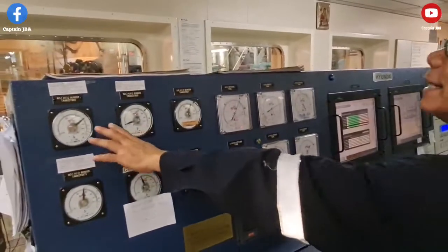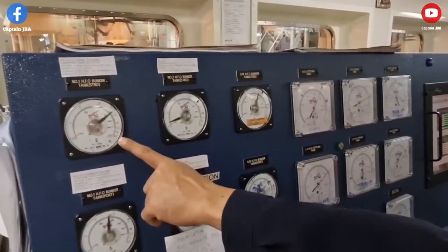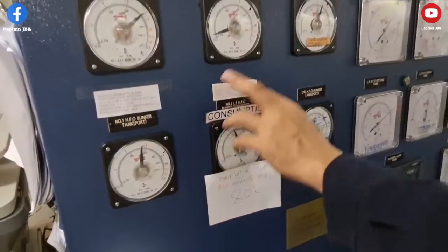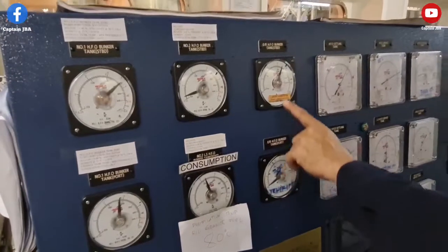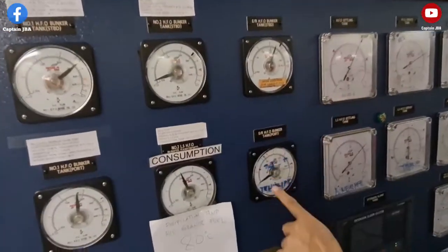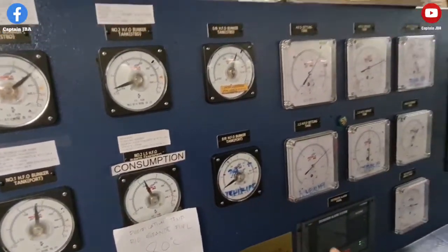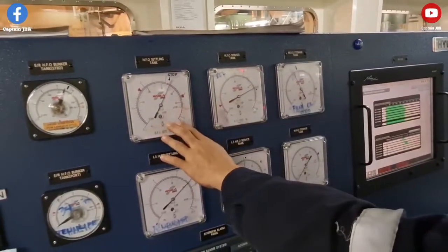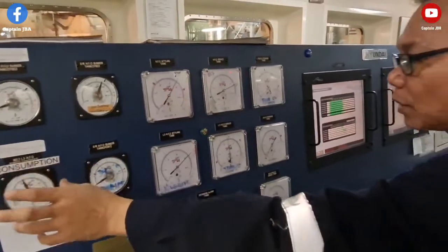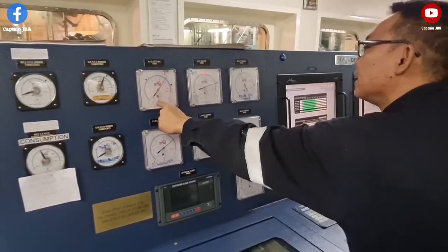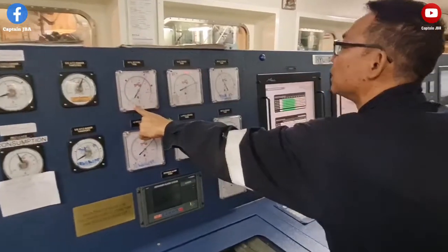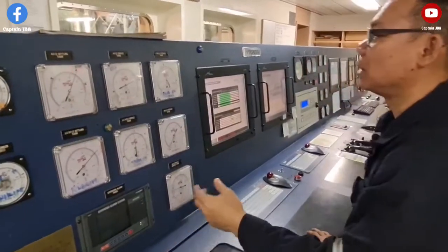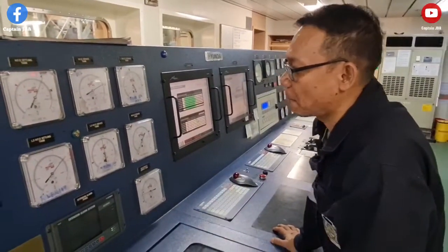So as you could see, we have number 1 starboard port storage tank, 2 starboard port storage tank, engine room starboard tank, engine room HFO bunker tank port, including those settling and service tanks where we could take the fuel from storage going to the settling, and from settling we're going to transfer into service tank through a separator or the heavy fuel oil separator.